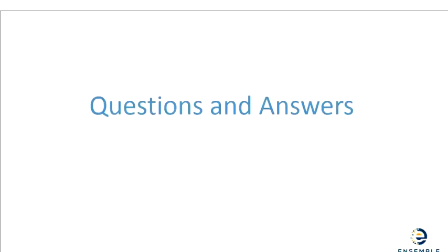And that is actually an important question, and for folks who are considering this, it's important to understand that false positives are going to be there. There is no 100% accurate predictive solution. If somebody's claiming that, they could have it, but that also means they could have false negatives. Now, a question you have to ask is: is a false positive more costly or a false negative, and what is the ratio between them? That will help you come up with the optimal number, and that's the discussion we have with customers. Having too many notifications can be a nuisance, but having too few notifications can also mean you're missing out on some of the predictive notifications.